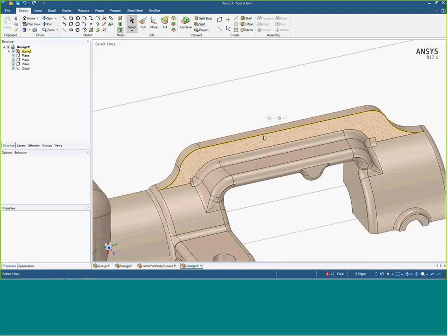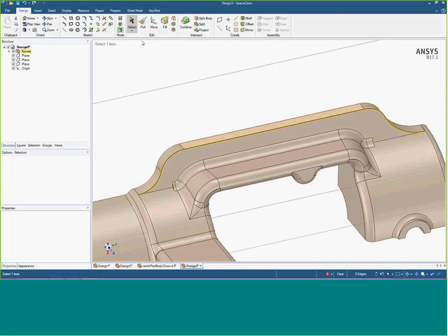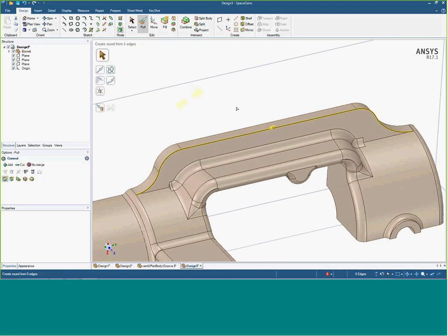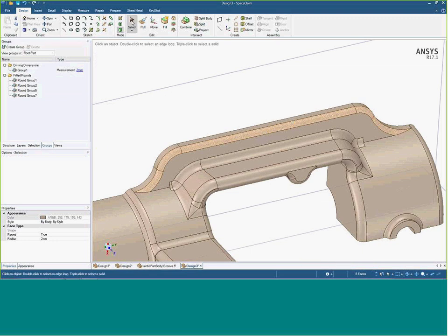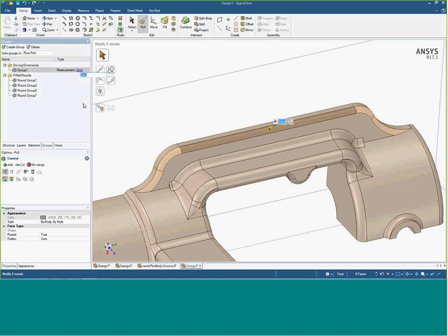And then I could also double-click this edge right here, and if we wanted to put them back in, let's say, you can use the pull tool, and then just, with the left mouse, drag it to the value we want, or hit the space bar, and then type in a value that we want that to be. And then anything that you type in, like a move, pull, that has a number like that, there's a little P that will show up next to it. If you click that, that's now a parameter, and that parameter gets stored under the Groups tab. And if you're not in any tools at this point, that gets saved, and we can edit it anytime.